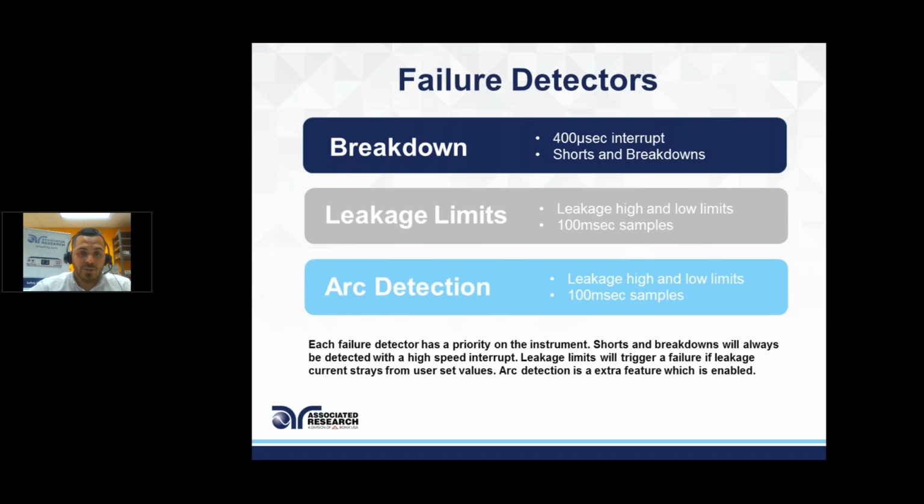But fortunately we have these IEC standards that regulate what the definition of a quality product is, what makes it safe for you to use. And while a lot of people maybe try to be a little more economical on the insulation they purchase, it still has to meet that minimum criteria of not breaking down at that voltage. So a breakdown, as we showed earlier, is just a large, complete failure of the insulation.